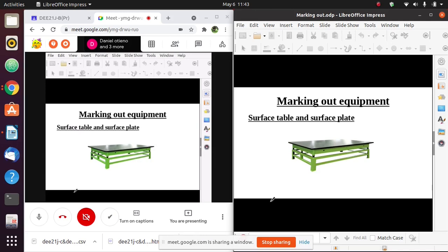Now, it is usually used to check the trueness of the flat surface of your workpiece. Reason being is because this table has been machined accurately. Its squareness and parallelism is accurate, such that from this edge to this edge, it is flat. It is completely flat, no hills and valleys at all. That surface is purely flat.